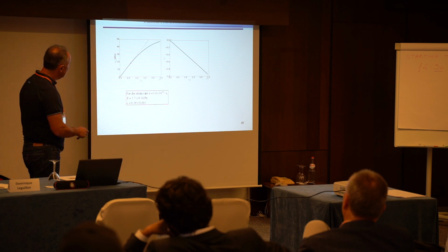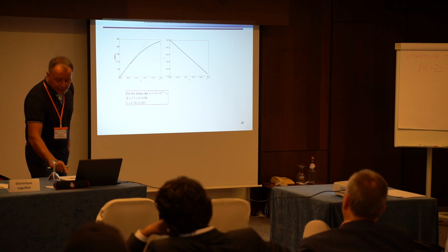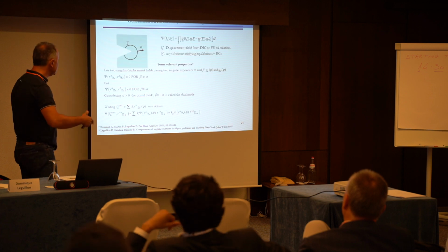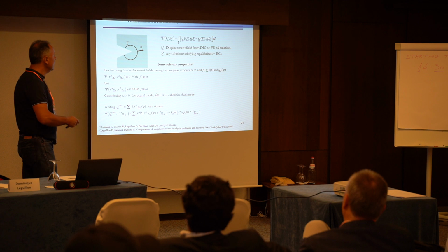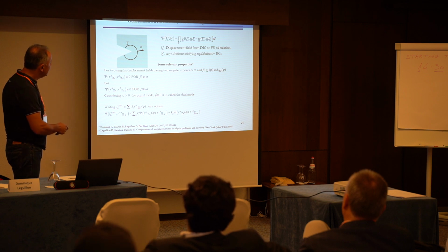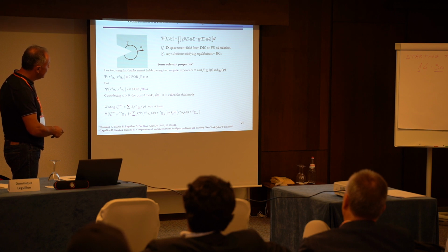You also derive the Poisson ratio, which was of course measured from an unnotched sample of the material under consideration. So with this, you have everything to go through the GSIF machinery, which involves an interaction integral, capital C. All the details of this are in the Leguillon and Sanchez-Palencia book.